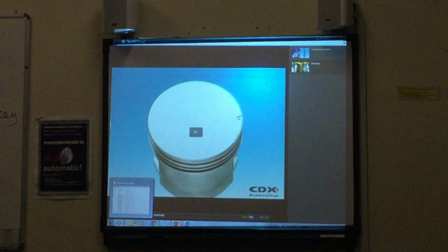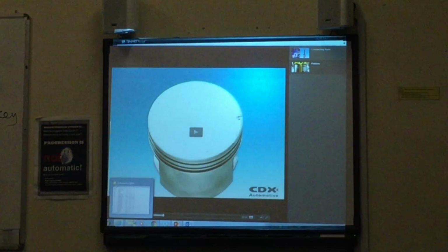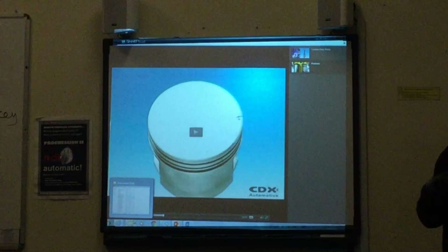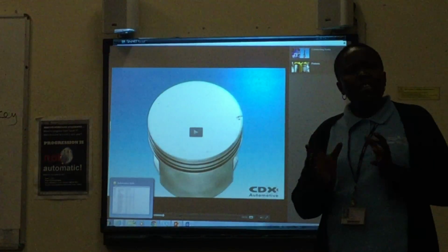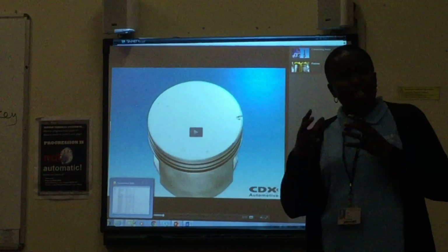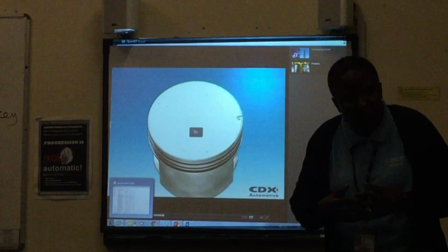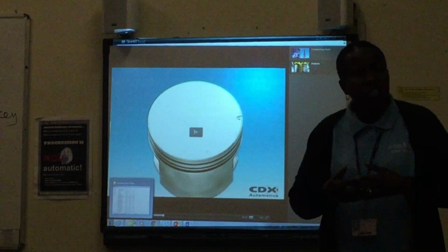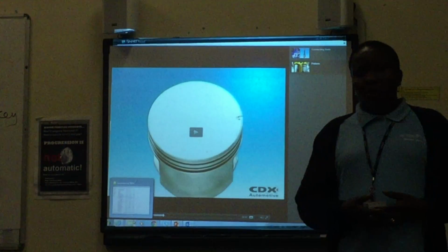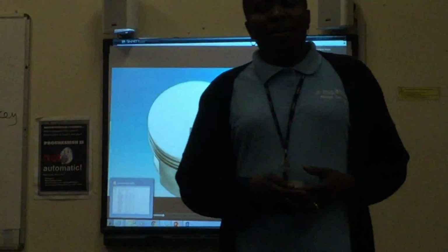Oh, I've got a question. What's the job of the flywheel? The flywheel keeps the momentum of the engine because it's a heavy wheel. During the non-firing strokes or when the engine is idling, the flywheel keeps the momentum, so it takes up the slack of the other pistons. Does it attach to anything else, or does it just sit there? It is attached to the crankshaft and keeps the momentum, but it's not attached to anything else. Also the clutch plate is mounted on the flywheel.